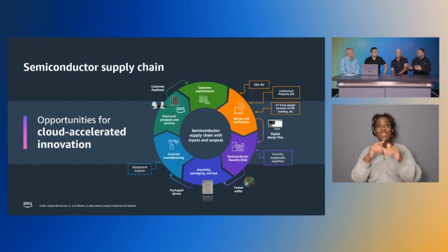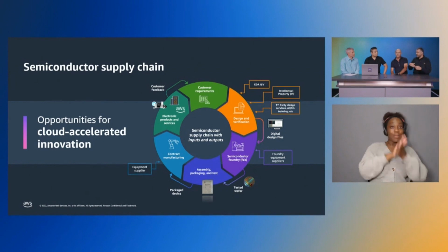And then after that, you convert that logical representation into physical representation, right? This is where you start to do actual implementation, place and route, and then timing analysis, power analysis, and then extraction, parasitics, trying to understand the impact of the physical geometries and the actual manufacturing process on the design. Obviously, there could be iterations in that process. For example, after synthesis, you found that your timing has degraded so much, so you go back to your code and re-optimize and things like that.